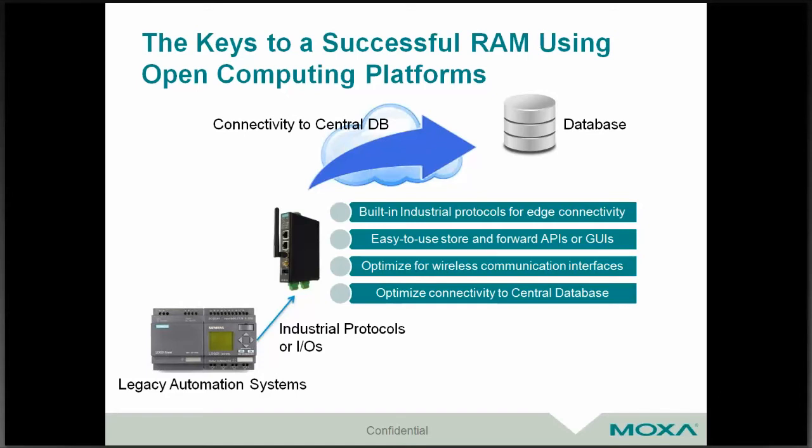So the computer platform needs to have an API or even GUI allowing the customer to set up the Modbus TCP or Modbus RTU communications between the PLC, RTU, and the computer itself.